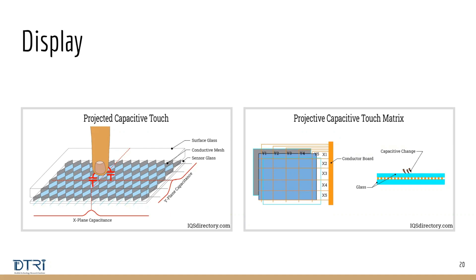And obviously this touchscreen has to be water resistant, dust resistant, and scratch resistant. So if the phone falls and it scratches, what happens? The top surface glass, if there is a scratch, you may not see much of a problem. But there is a conductive mesh or the plastic surface below that. If that gets damaged, then your touchscreen does not work, because the surface glass is still a protective layer, but below that is the actual electrical part. So if you have a scratch on the surface, it may still work, but if it gets cracked, then it won't work.